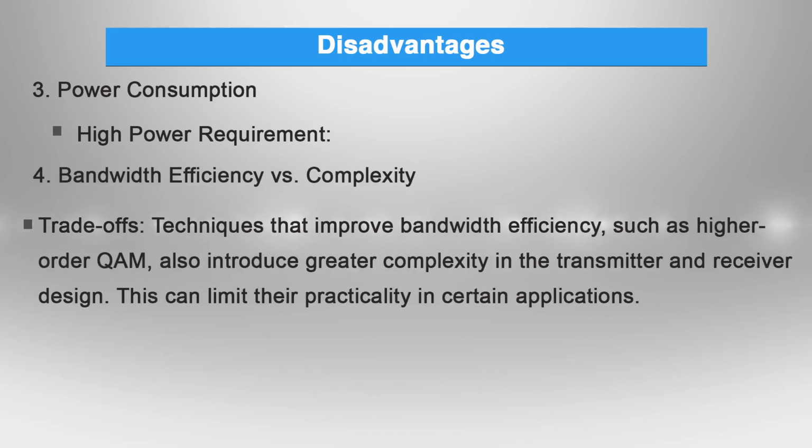Next is bandwidth efficiency versus complexity. Techniques that improve the bandwidth efficiency, such as high order QAM, also introduce greater complexity in the transmitter and receiver circuitry. This can limit their practicality in certain applications.